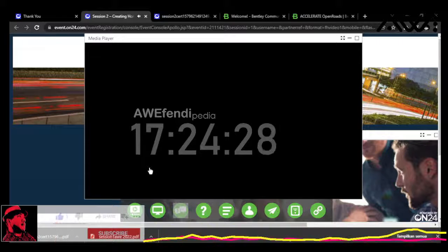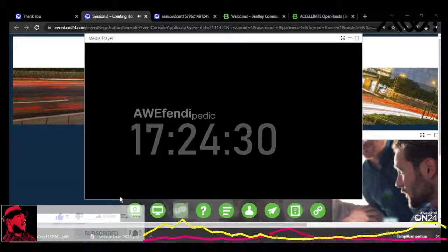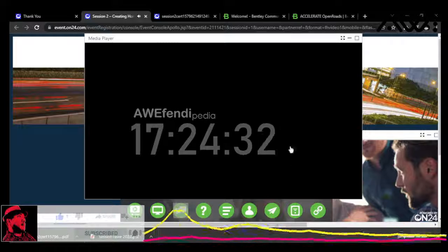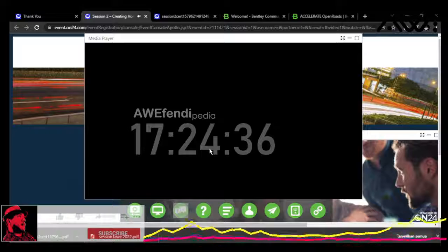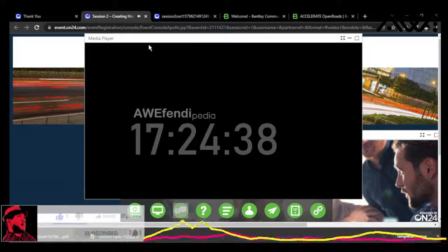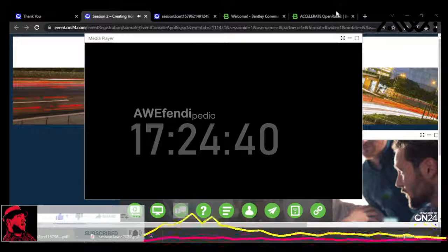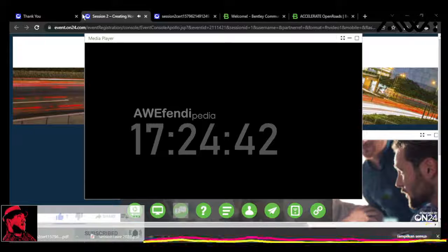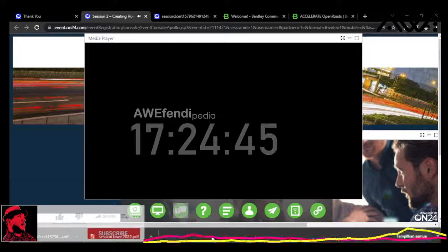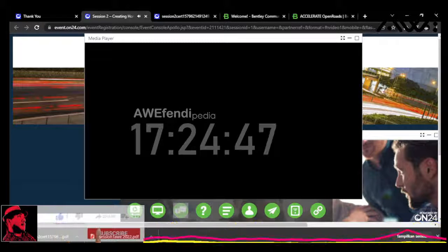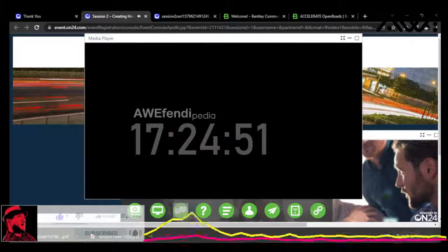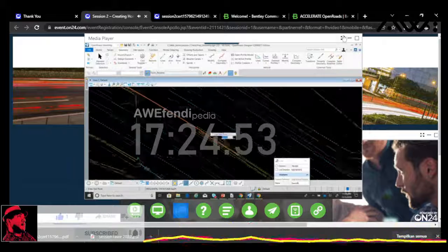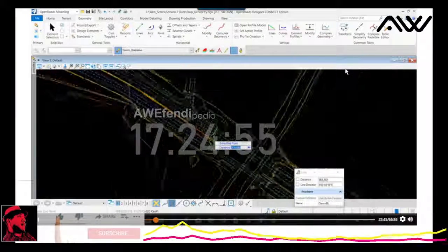So we're going to place the next tangent element that is going down. It's 2,000 feet long that goes across the bridge and into the next curve. We have the bearing, and we have the length as well. So pop that open. Again, we'll go back to place that horizontal tangent section. I'm going to snap that graphically. So I'm using a MicroStation snap and place this down this way.